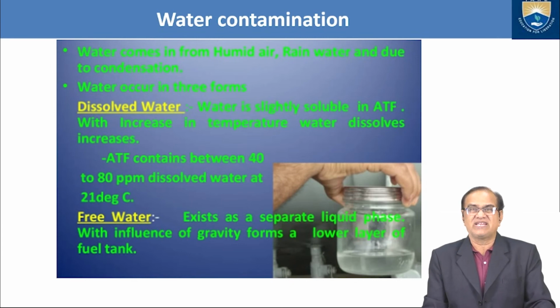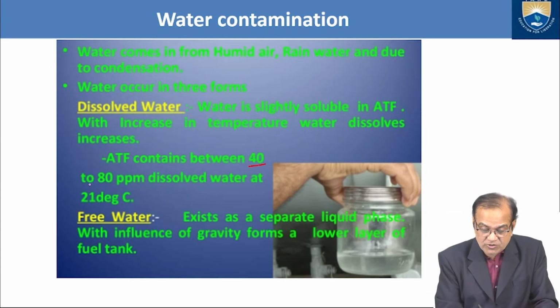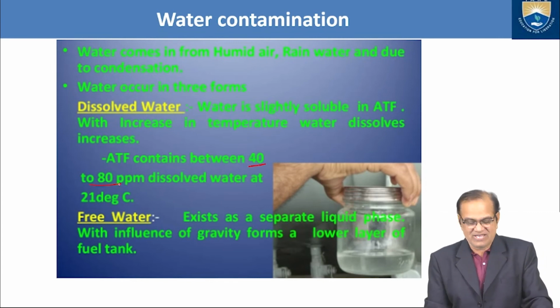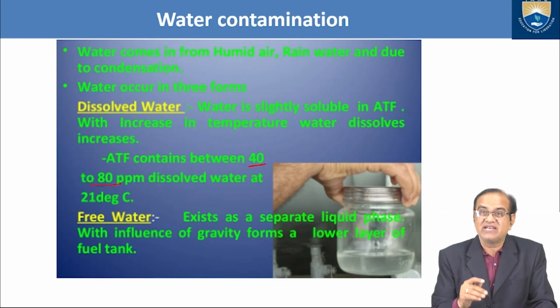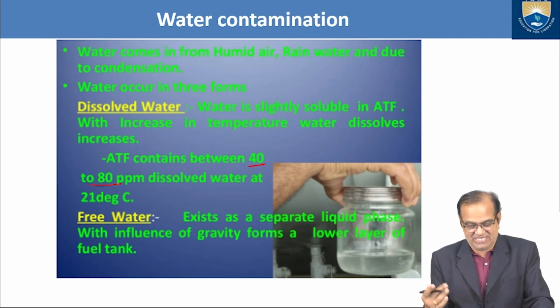the dissolved water increases. ATF contains between 40 to 80 ppm dissolved water at 21 degrees centigrade. So ATF will have 40 to 80 ppm. We have to make sure that the water is not present more than this.